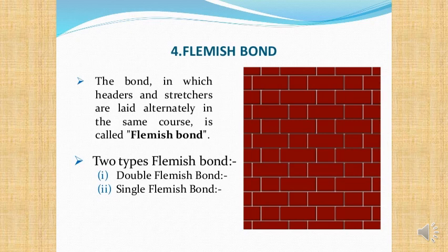Final thing, one of the big advantages a Flemish bond will have over an English bond is you can actually use bats. You can actually break the bricks, the blocks, and have them on the end. And so labour is a lot easier than with the English bond.